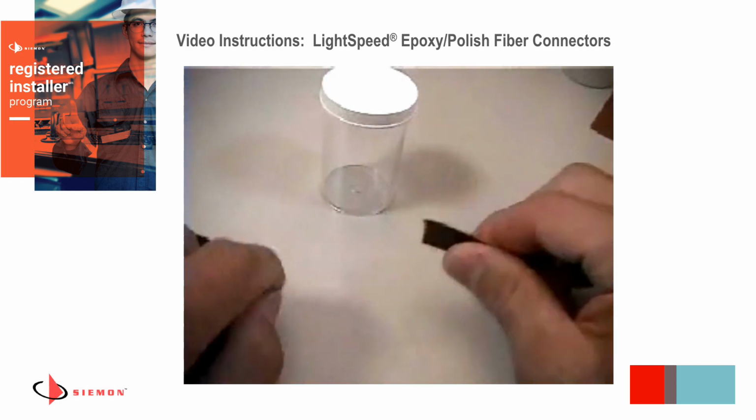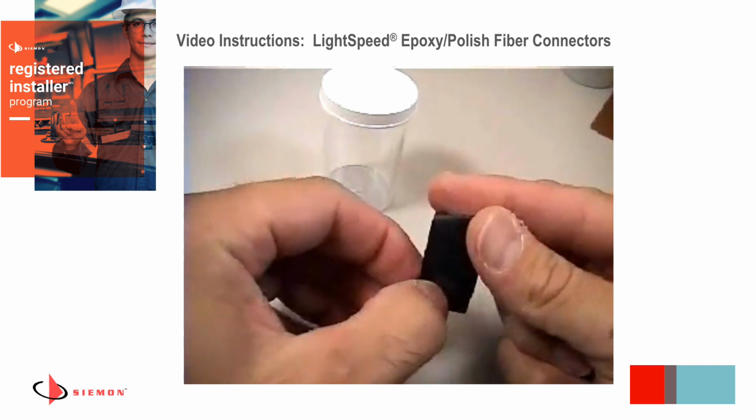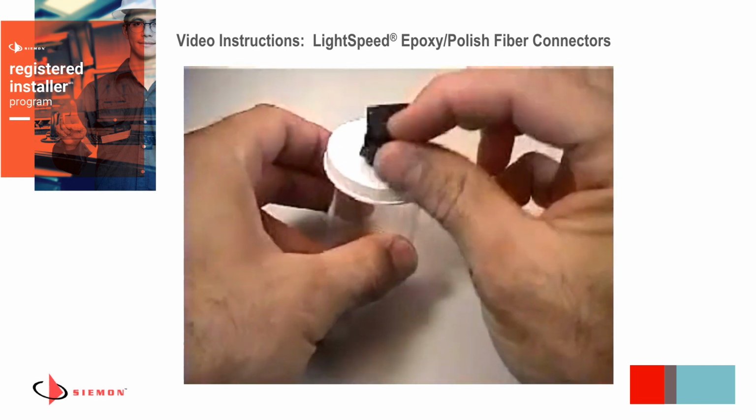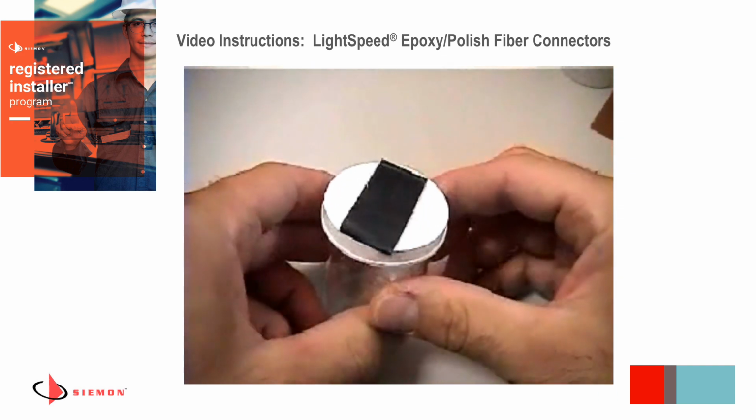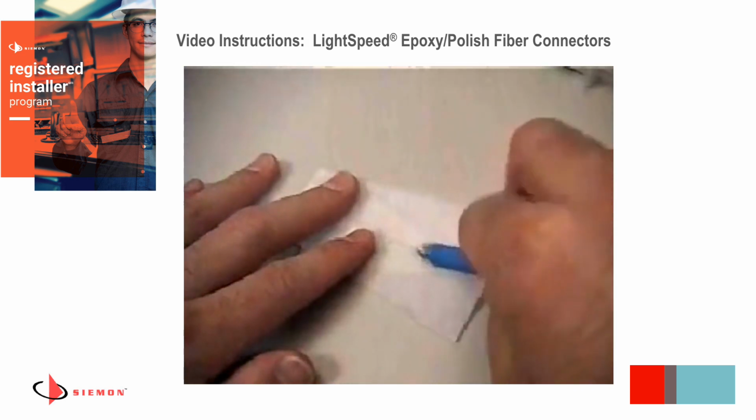Be sure to keep track of your fiber pieces. They are difficult to see, and if these glass fibers are not properly disposed of, they may cause serious injury. Also remember to clean any adhesive off the blade of your scribe tool before it dries.